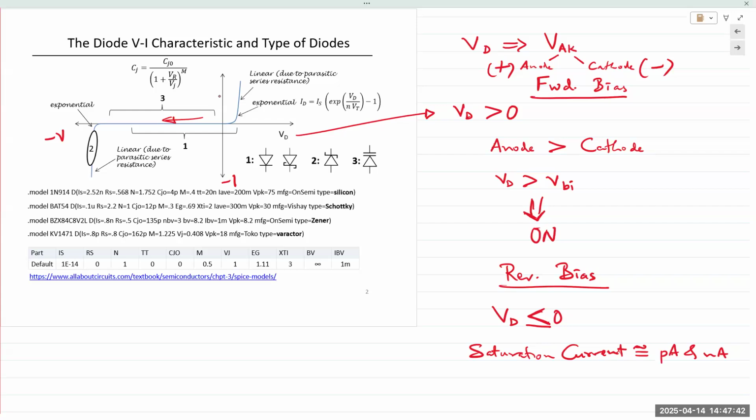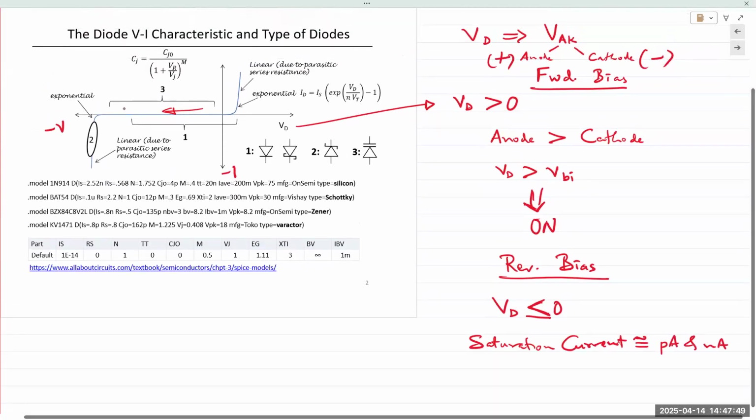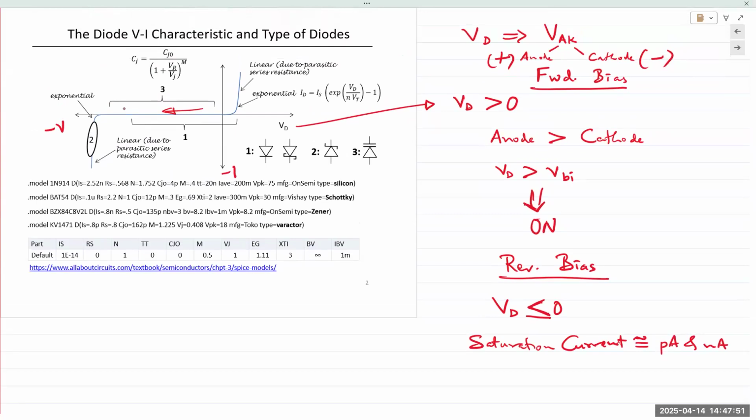Experiments with diodes in reverse bias. The other thing that happens is it must withstand it without the junction breaking down. So what does breakdown mean? Breakdown is something that occurs in reverse bias when the voltage that is applied in reverse bias to the diode exceeds a certain level. Say junctions.